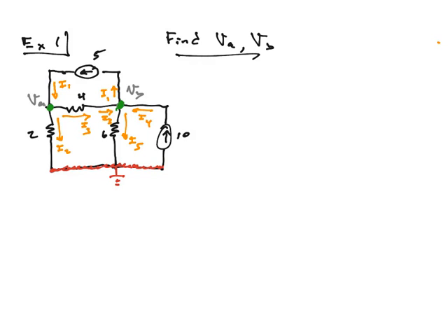All right. So I've now labeled the nodes and showed the currents coming into and out of them. Next is to do my equations. So let's do node A first, and I'll do this in a very organized manner. Node A. Sometimes it's helpful to show what node A looks like. Here was A. And what did we have? We have I1 coming in like this, I3, and I2. Right? That's what node A looks like.